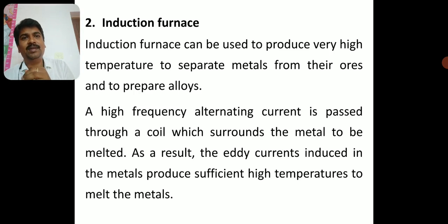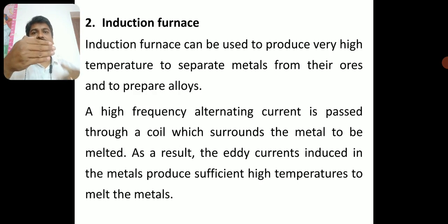How actually the temperature is produced in the induction furnace, we will see. The principle behind this is the eddy current. A high frequency alternating current is passed through the coil, and the coil is surrounded by the metal to be melted.